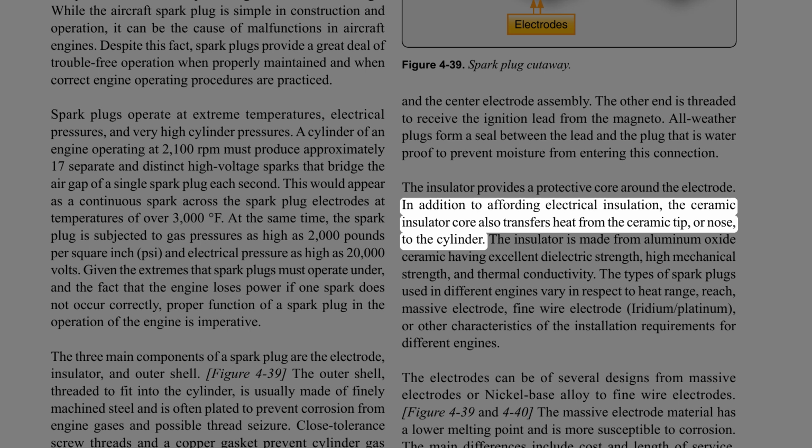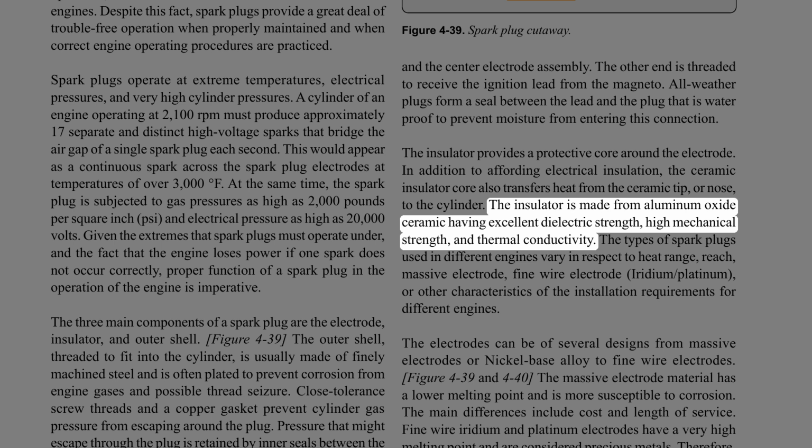In addition to affording electrical insulation, the ceramic insulator core also transfers heat from the ceramic tip, or nose, to the cylinder. The insulator is made from aluminum oxide ceramic having excellent dielectric strength, high mechanical strength, and thermal conductivity.